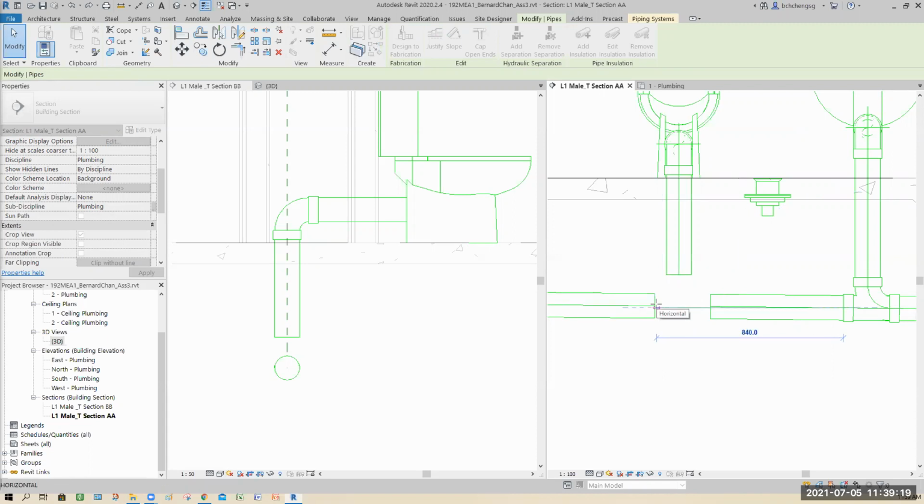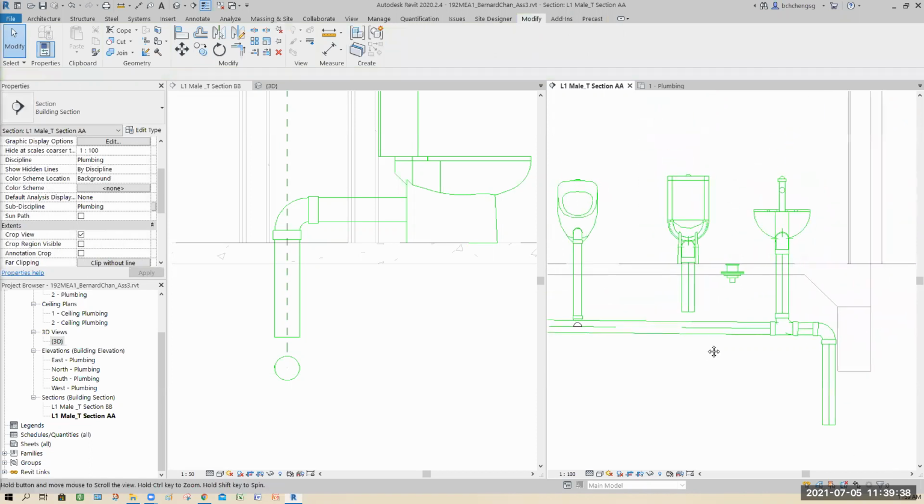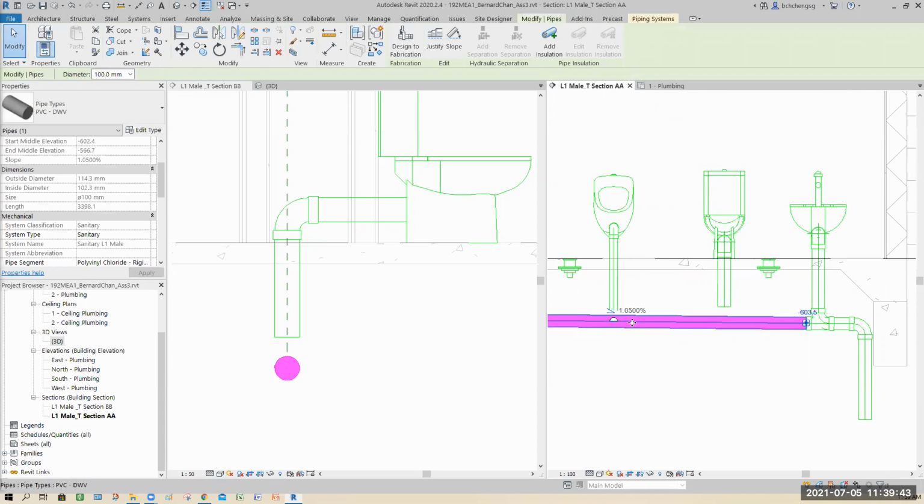Not like that. This is horizontal, wrong. You don't maintain the 1.05 sloping. So this way, fidget a bit, make sure it's like this. Parallel and nearest. If it's correct, you let go. Your two pipes should be connected as one. Once connected, you select them, you should see the percent. Sloping percent is still maintained at 1.05. At least in your paper, so-called your drawing, is correct.